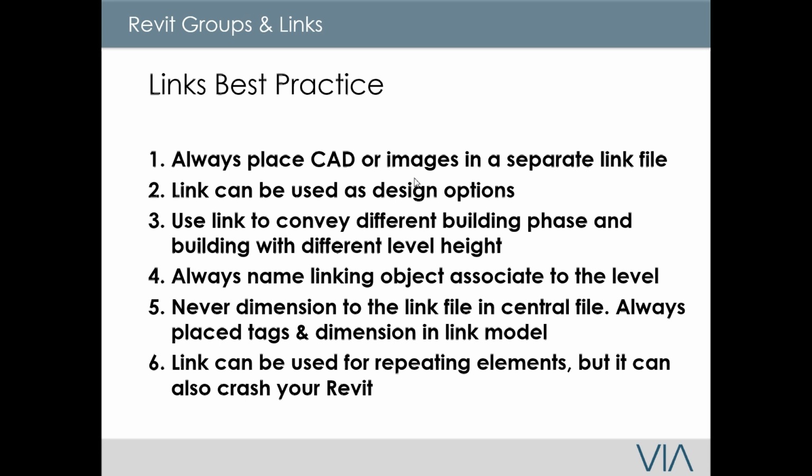When you upgrade projects, sometimes this will come back and haunt you. I just don't recommend it. If you want to do it because you think it will save you time, it doesn't really save you any time. So what I typically do is put those tags and dimensions inside the link model, so that if someone accidentally unloads the file, you can always recover it.